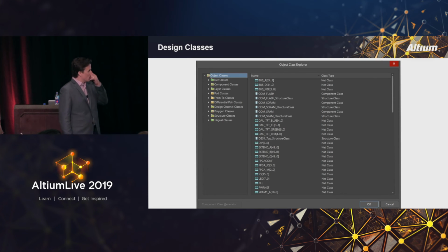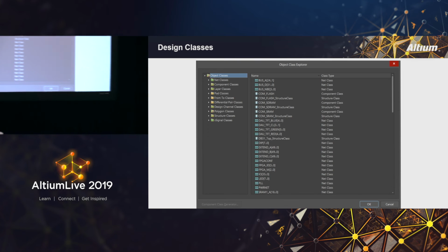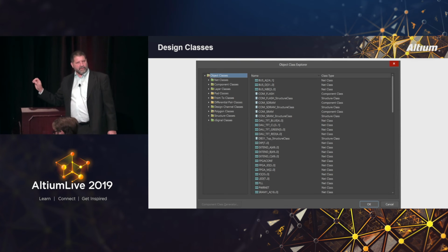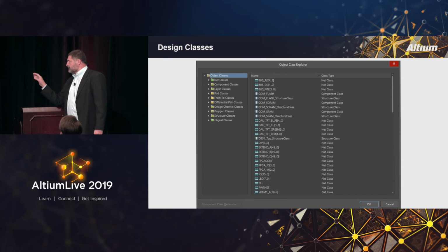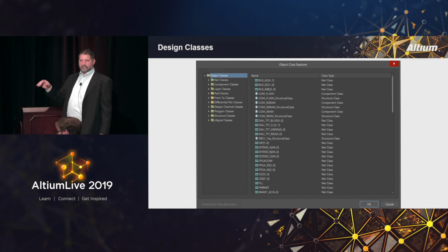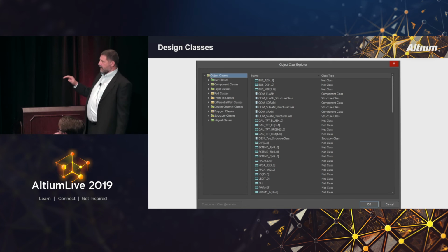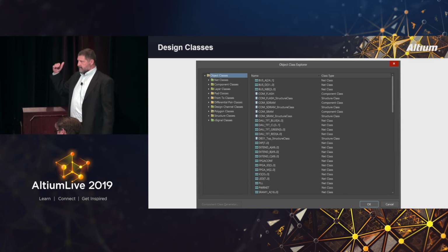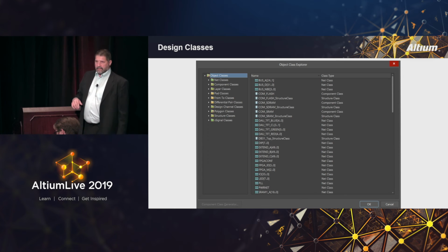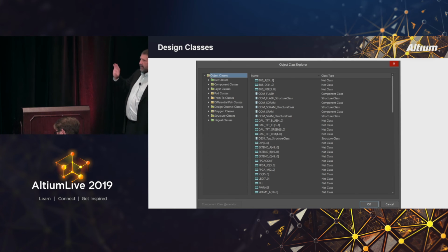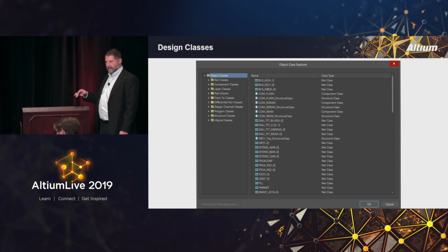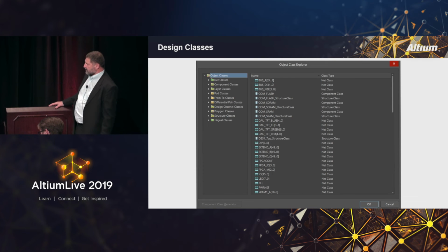So we bring in the classes from the schematic, net classes, PCB classes. You're going to create pad classes in your board, usually a non-plated hole needs to be 0.3 millimeters away from copper. Those are the kind of rules that are set up in the PCB after the schematic comes in. Binary type rules, where it's something to something else. The class rules would be set up there. And there's really good information on Altium's website about how to do all that. I don't think we need to cover that.